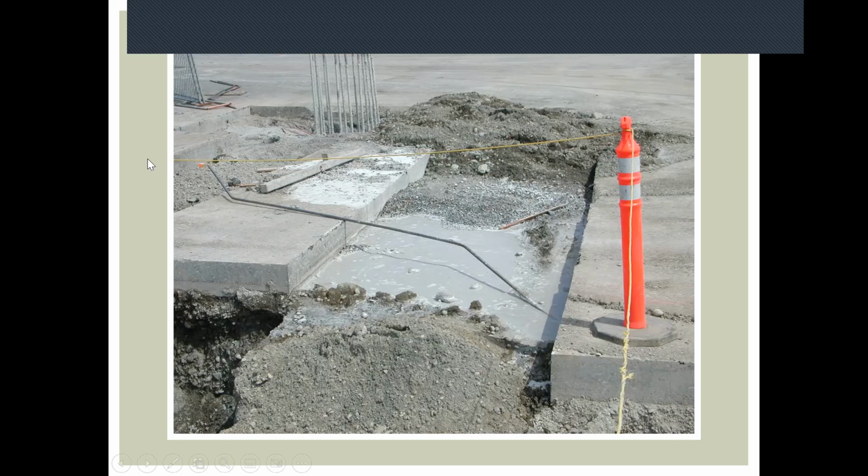Concrete management. This used to be allowed, at least in the state of Washington. If you were going to be pouring concrete later, you could wash out in an area. This isn't allowed anymore. So look for these sorts of things and work with the contractor on better ways to manage it, like washing into pans, for example, or in some cases on a large pour where the batch plant is close enough, within 20 minutes or so, just have them not wash off and take it back to the plant, wash off there.